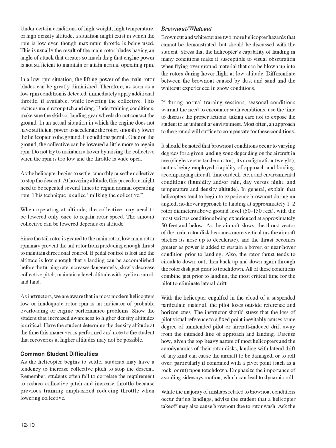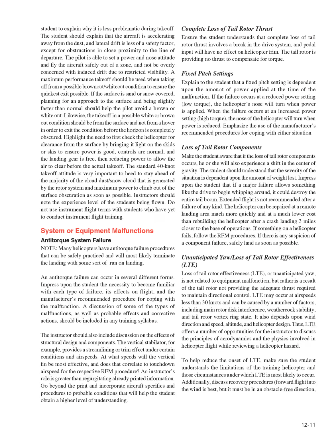While the majority of mishaps related to brownout conditions occur during landings, advise the student that a helicopter takeoff may also cause brownout due to rotor wash. Ask the student to explain why it is less problematic during takeoff.